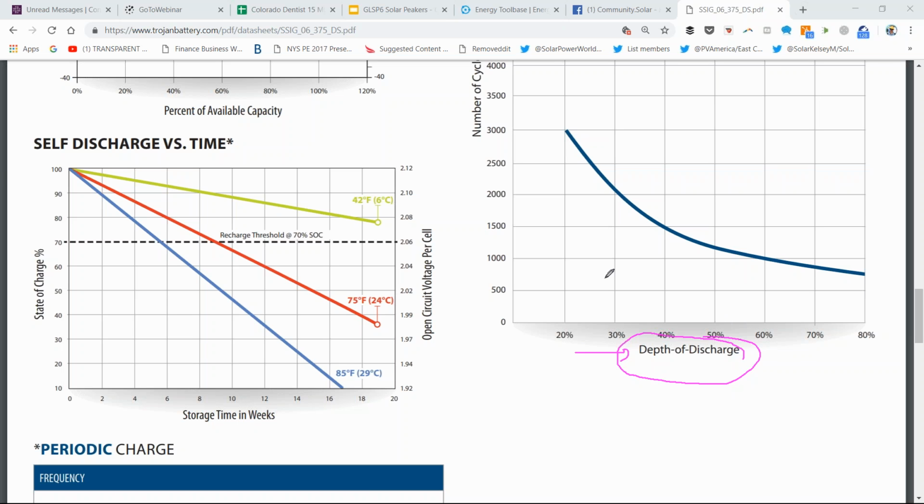Often in the off-grid market, we'll design a battery to take the house 2 or 3 days off-grid, and so its average usage is not going to be, at the day 3 mark is when you get down here. So on a typical day, you only get to maybe a 25 to 30% depth of discharge.